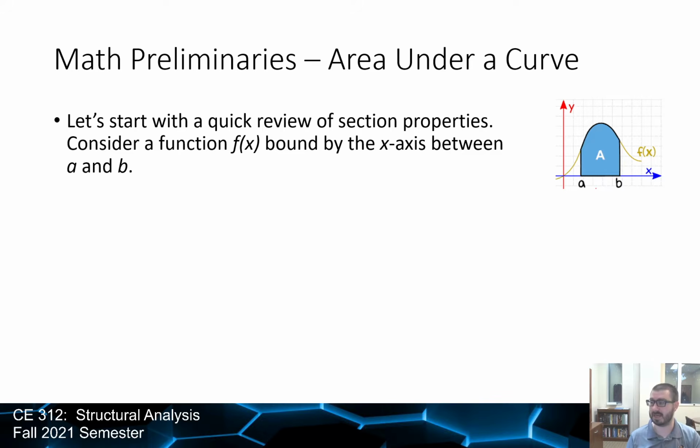What I mean by a section property is, if I have some shape, some bounded region, what are some numerical properties that define that region, such as the cross-sectional area, the location of the centroid, the moment of inertia. If you look at the handout that I gave you in lecture 15 on the analysis project related to the W12 sections, that was from the steel manual. It was just a list of all the section properties that characterize certain I shapes. And those numerical properties are what we use to classify their resulting behavior. So we start off with basic.